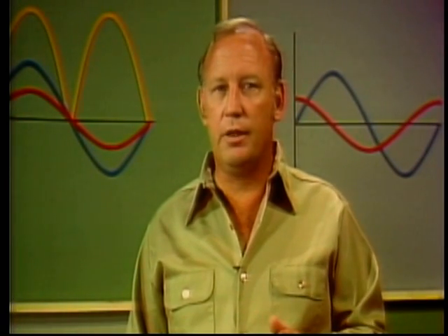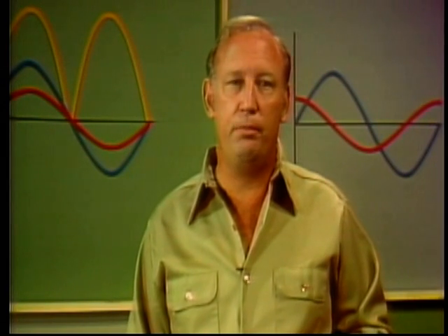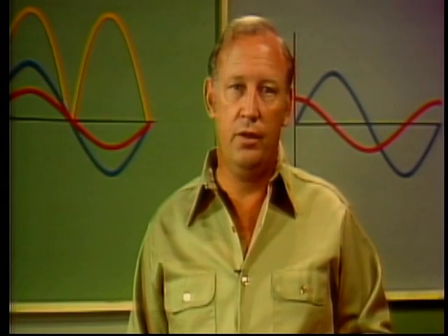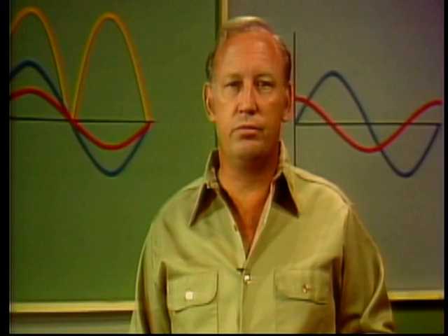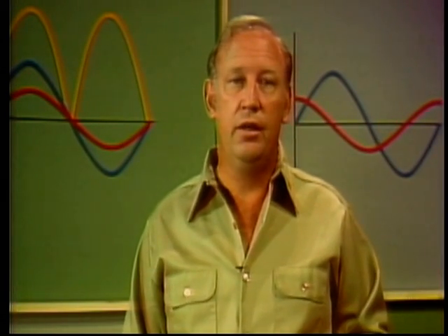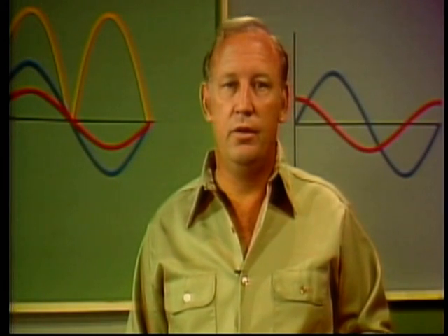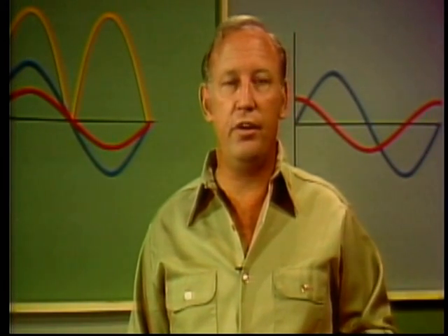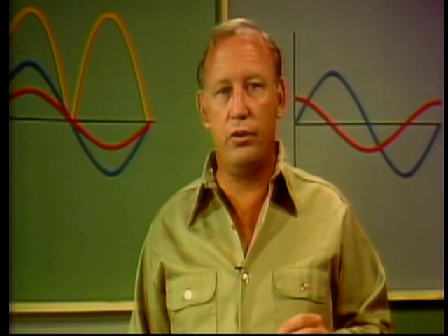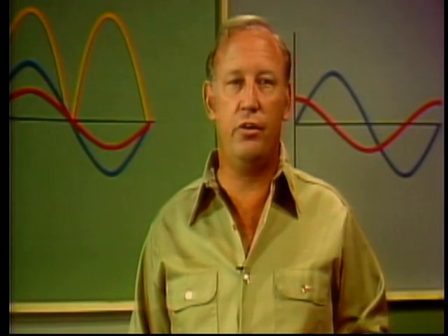Current flow is actually limited by an induced voltage that opposes the applied voltage. This induced voltage is called counter voltage, or more commonly, counter electromotive force, CEMF. CEMF is caused by self-induction. That is, the induction of voltage in a wire by AC current flowing through that wire.